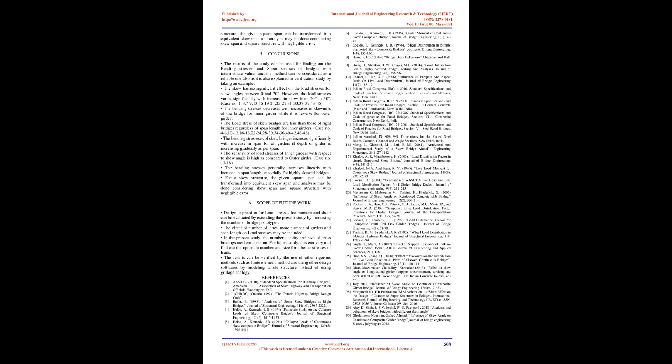Case No. 1-3, 13, 15, 13-21, 25-27, 31, 33, 37, 39, 43-45. The bending stresses decrease with increase in skewness of the bridge for the inner girder, while it is the reverse for the outer girder. The load stress of skew bridges is less than that of right bridges regardless of span length for inner girders.